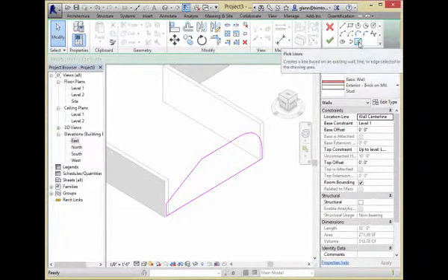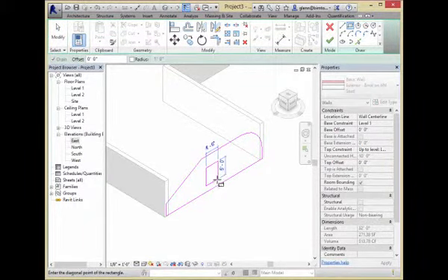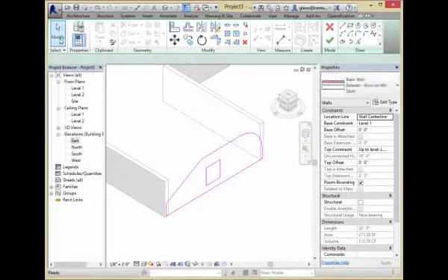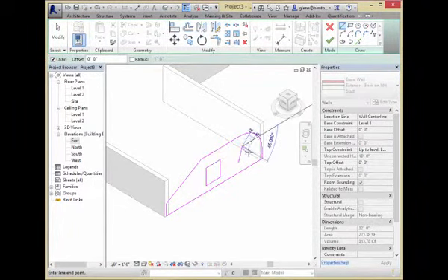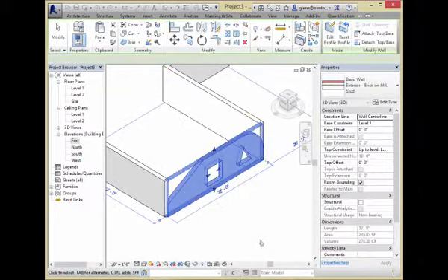So the boundary will always create positive geometry. If you go through and put an interior boundary, that'll subtract space. Okay, and that's going to come in useful here, here, here. Whenever you want to put an opening in something, you take the outer boundary and you put a hole inside of it, and it'll subtract space out. Okay. So similarly, I could do just pretty much any shape I want. If I want a triangular opening, I can just draw a triangle on there. Okay, and that'll hopefully cut a hole in there.